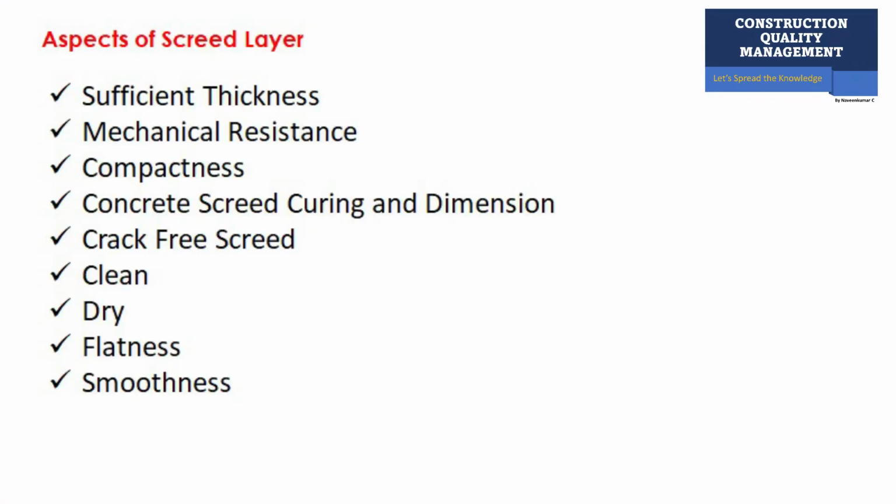What are the aspects of this layer? Why do we need it? What will it serve? One is sufficient thickness, mechanical resistance, compactness, concrete covering or a closure or envelope, flatness, smoothness. These are all the aspects and the need of this screed layer.